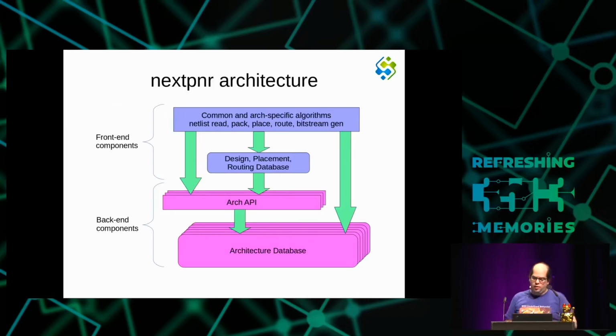So in a couple of scenarios, you might have different routers. You have architecture-specific routers that do specific clock routing tasks or things like that, and then you might follow that with the generic router that routes all the ordinary nets that are remaining, depending on what is good for the architecture that you're targeting.